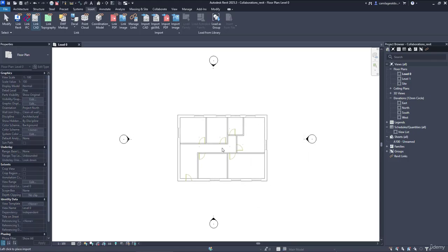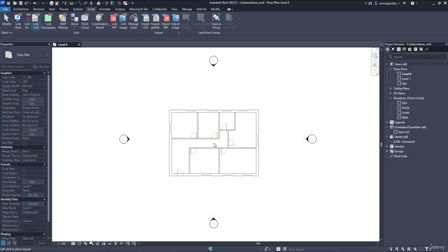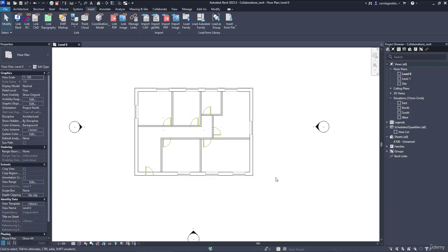This is the CAD drawing, and as you can see, we are moving it from its center, and we just need to click where we want to place it. Nice! So, linking a CAD file creates a reference instead of attaching it directly into the project. This is usually preferable when several people are involved in a project. For example, an architect making the floor plan and then an interior designer using Revit to make the furniture layouts.